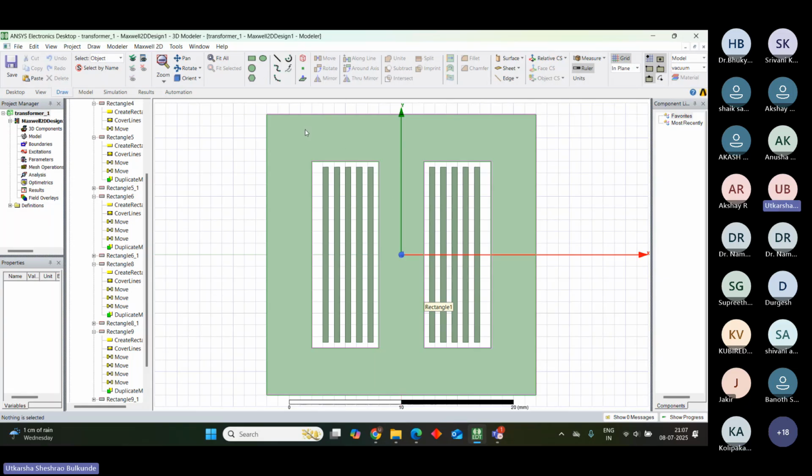So first understand how you are positioning the things. Second, understand how you can cut objects from your geometry. And third, try to use the duplicate option and move option. We will use these options a lot, that's why I'm telling you. It's fine if you don't understand Unite and all, it is for our convenience. But the move option, subtract option, and how we are positioning the object are very important things to understand.